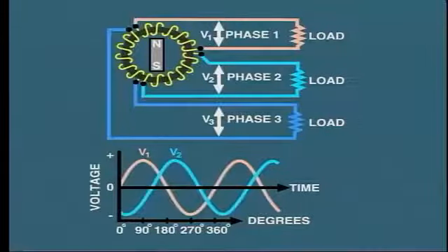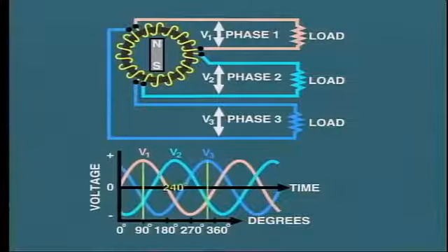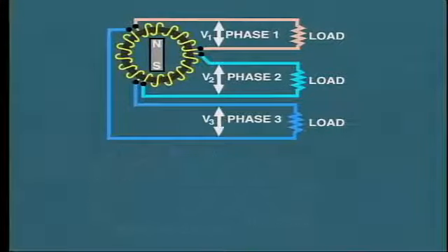This too can be connected to feed an individual single-phase load. And similarly, its voltage generation cycle is 240 degrees out of phase with phase number 1. So what we have in effect here are 3 independent windings supplying 3 independent loads, but each using a common iron core and rotating magnetic field. Almost 3 generators in one. But there is a further advantage.